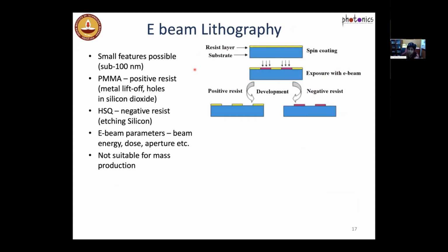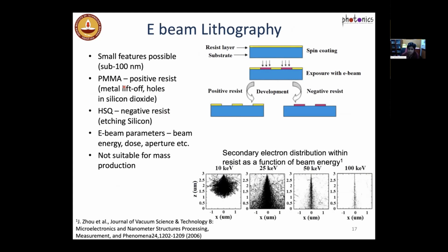So we want to do sub-wavelength structures. You have different means of transferring. You could use a positive photoresist, which is what we do. But then this means you need to have a lift-off and subsequent etching. You could also use a negative resist mask, but this is not what we have done. And the electron beam lithography parameters all have to be very carefully optimized.